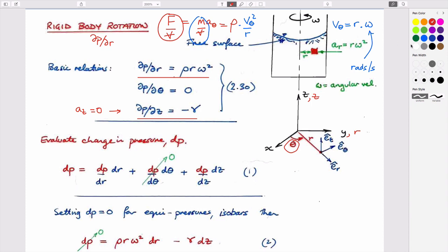And so what we'd expect is that at any given angular acceleration, well, first of all, r equals 0. This has to be flat, right? I'm going to choose a color that will show up on here. Right in the middle here, this gradient is flat, which means if r is equal to 0, the pressure gradient has to be 0. If we go radially outward a small amount, there's no pressure change. It's flat. If we look at the pressure distribution at some radius here, which is r1, then the pressure gradient might be this. And if we go out here some radius r2, then it would double, be twice as steep.